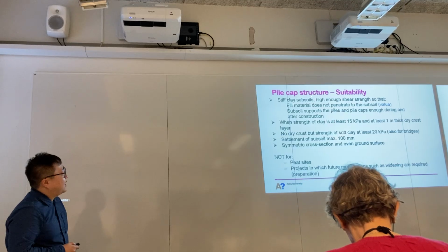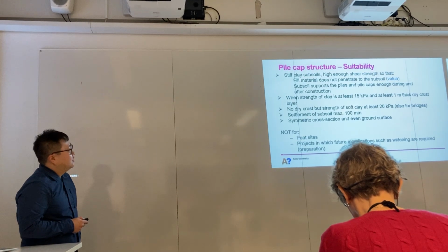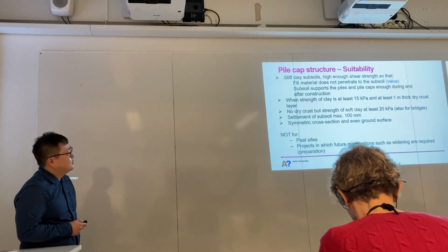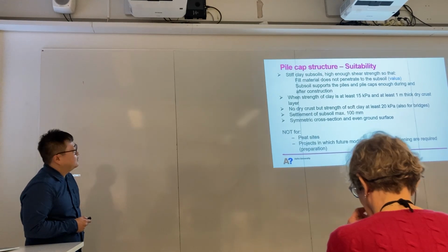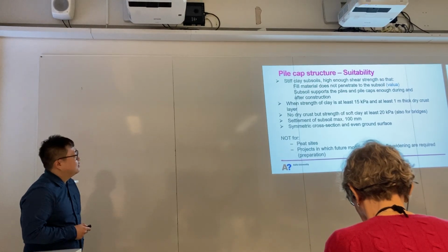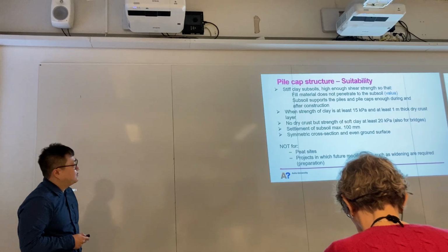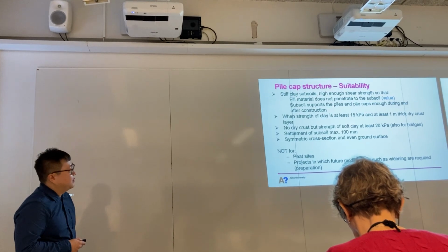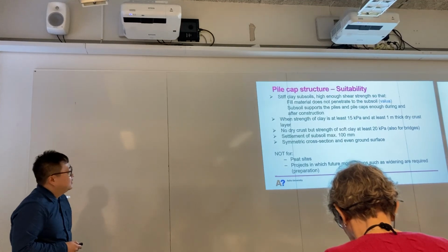But the pile cap structure is not a continuous slab, so it's limited to some situations. It works well for stiff clay subsoils with high enough shear strength, so the fill materials cannot penetrate the subsoil, and the subsoil can support the pile cap structures enough.